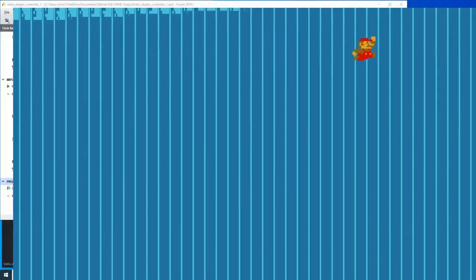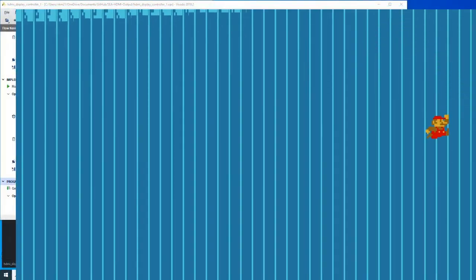And in the Y coordinate, what I mean is, if you look over here, it's hard to see, but it's a darker color here, and everything is downshifted a little bit. So you have a little bit of a light blue color over here in the first column, and the same thing on the top. That first pixel is darker, and then the rest become the right color again. So the implication to me is exactly that. We're loading data, and we're not loading data in advance. Our pixel clock is ahead of the RAM; the data isn't ready. It's not loaded in a register, so things are just changing a little, all over the place.